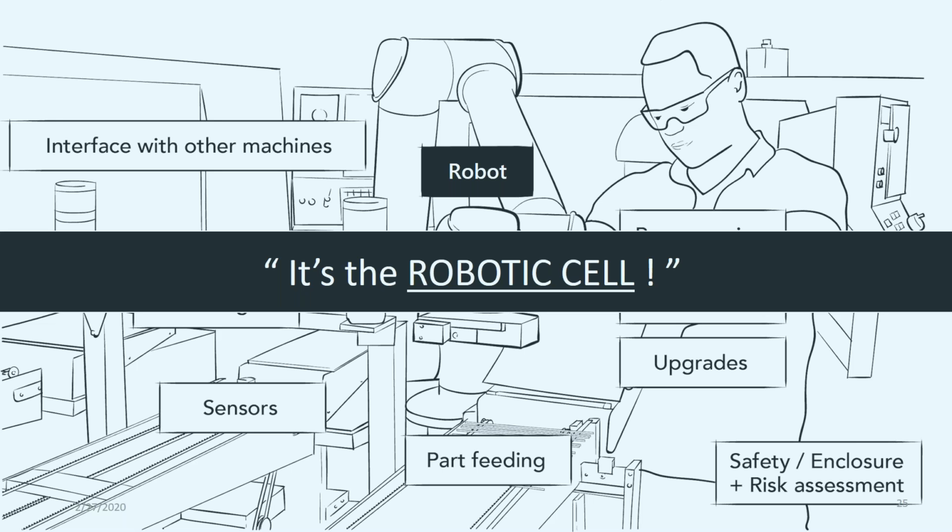Yeah, exactly. And that's a key thing to consider. Let's say you have a $50,000 robot, the hardware itself, the robot and the controller. Your robot sales guy comes out and says, this is a $50,000 piece of equipment. When it's all said and done, once you've added all the sensors, once you've had a systems integrator, or you've done the programming yourself and written the code for the robot, and maybe you've added a vision system, you're definitely going to need some mechanism to feed parts to the robot, whether it's a flexible feeder, or a vibratory bowl feeder, or conveyors. You're going to need some sensors to tell the robot that a part's in position, ready to be picked up.